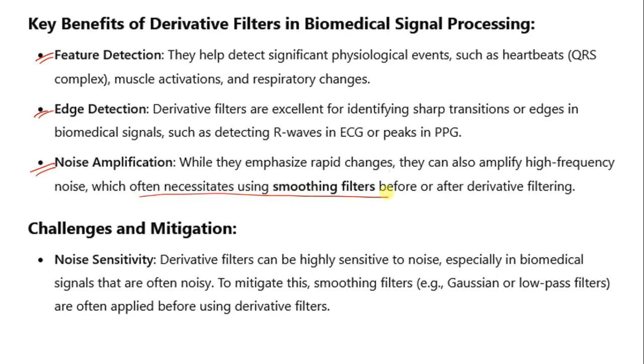When you apply the smoothing filter, you are basically suppressing the high frequency components. If they are noise, that's fine. However, if you have some high frequency components within the signals that are getting suppressed, then the high pass derivative filters can allow the strengthening of those signal components.